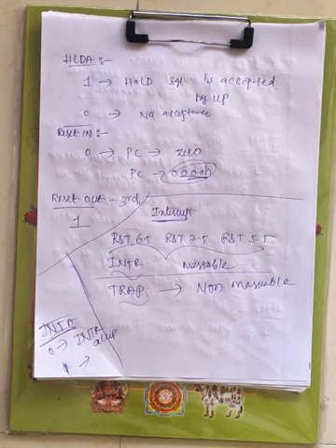You will have a separate topic on interrupts. Meanwhile, interrupt is to stop the process of the microprocessor. We have five different types of interrupt. Some are maskable, meaning we can disable them by writing an instruction. Some are non-maskable, meaning we cannot disable them once generated. If the interrupt signal is accepted by the processor, we get an active low signal on INTA, the interrupt acknowledgement signal. If it is not accepted, it is active high.